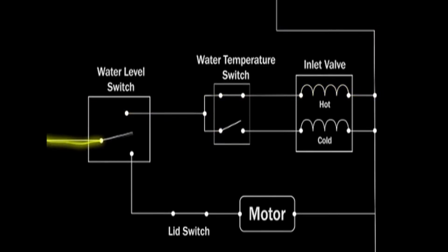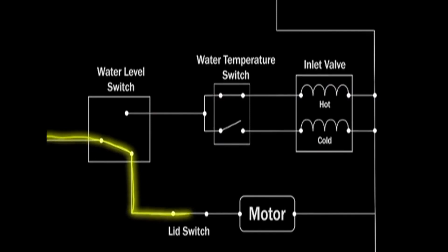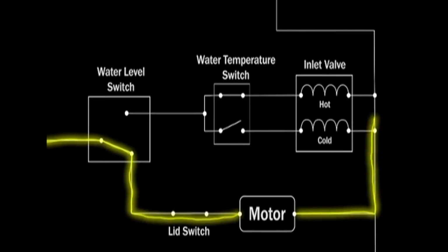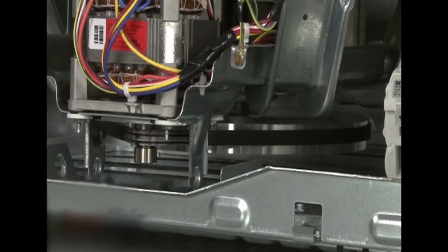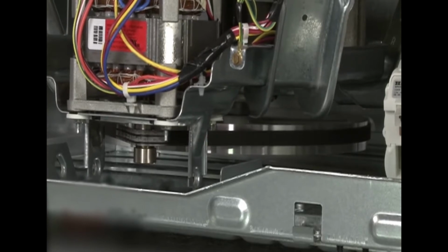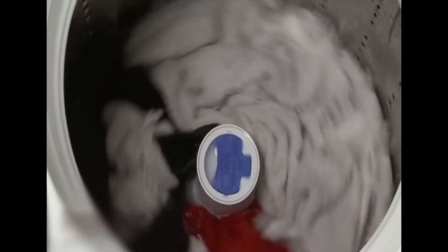When the motor is reversed by the controls, which is like spin, the transmission locks up and the agitator, transmission and spin tub all rotate as a unit. Changing the speed or direction, the unit uses centrifugal force to remove as much water from the clothes as possible. The motor is also connected to a pump. When the motor is moving in the spin direction, the pump removes the water from the tub and discards it through the drain pipe.